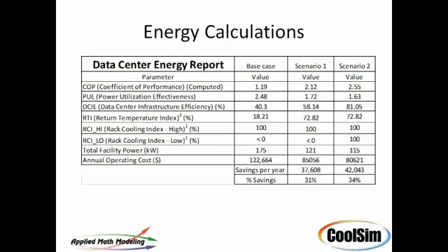And down below, we've got RCI high and low at 100 with our RTI at 72%. Now, we could try, Liz, to drive that a little harder. Right now I left it at a supply airflow of 15,000. The racks only need 10. But as you know, you will get to a point where you start to hurt your RCI high. You'll start to get some racks that are falling out of compliance. So this is a pretty good job right here.